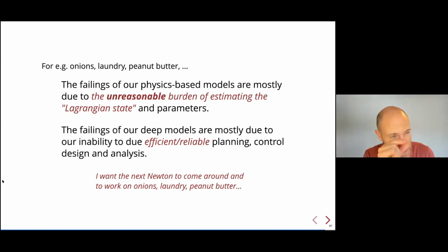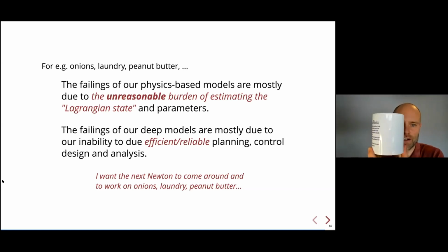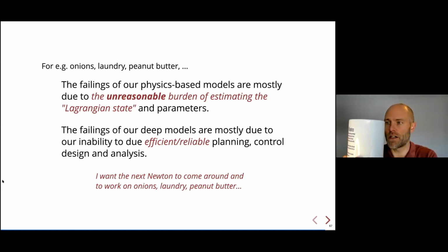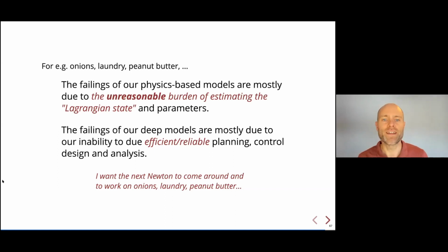Yeah, that was both very specific and very big. When it comes to uncertainty over distributions of pose, for instance, one of the things that happens a lot in these problems is you have some symmetries in your geometry. Your mug looks the same here until the handle becomes visible, and then it becomes interesting. So how do you write a distribution for that? I like Bingham, but I think there's something more going on there too, quite characteristic of these geometries. It has pieces of rotational symmetry, but it's not completely symmetric. We've used tools to think about that, like even numerical differencing on rendered images, which give you a sense of how you can do that.